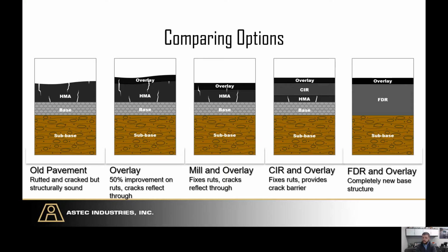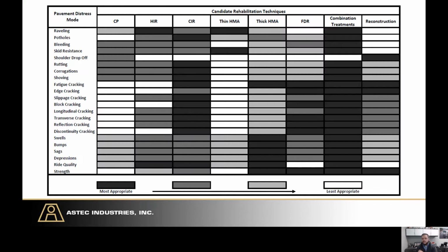farther. Then you have full depth reclamation, where we're really reclaiming the material, reclaiming the pavement, and rejuvenating it to the point of it being a new base. And you can see that there. So this is straight from the ERA Basic Asphalt Recycle Manual.